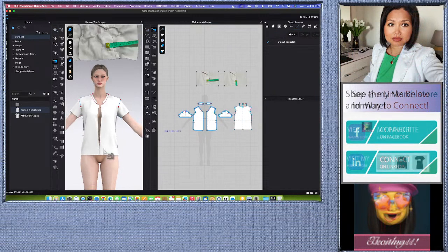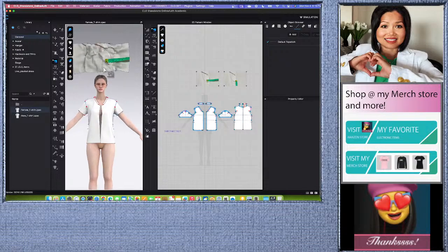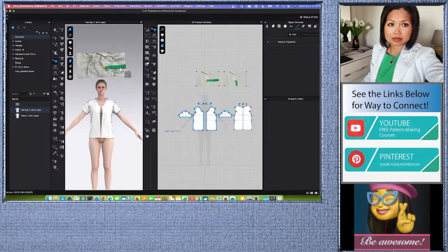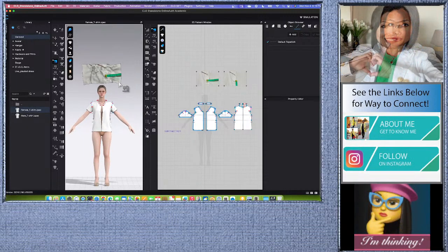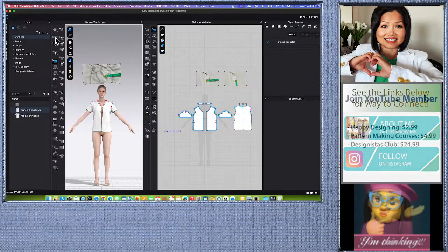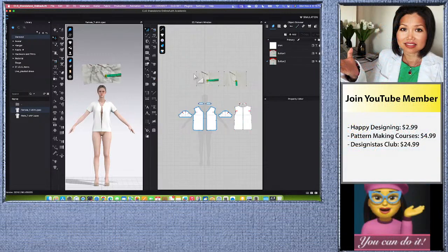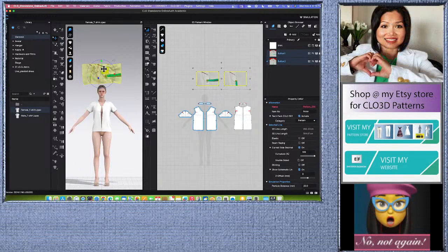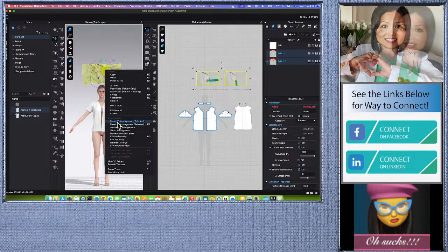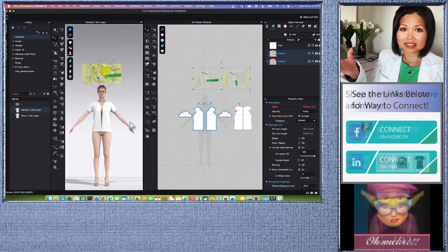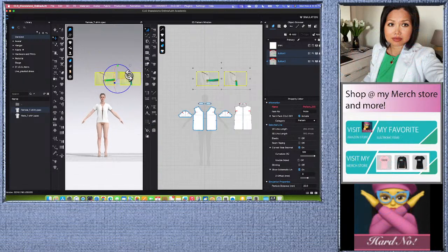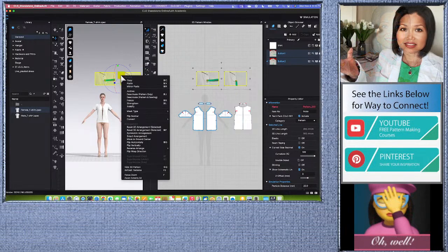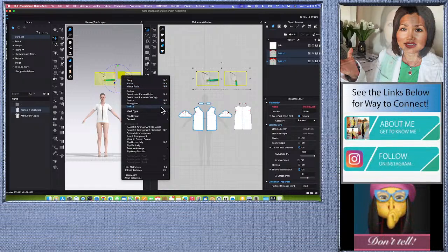Alright, so something I forgot to do here. Up here, the pattern, I want to freeze them so they don't fall on the floor. However, if they fall, it's fine, you can reset them. But right now, let's do this. Click on the select/move tool here, and select both of these patterns. Right click, and select reset to the arrangement. Now this pattern is back up here, and while these patterns are selected, we right click on them, and then select freeze.